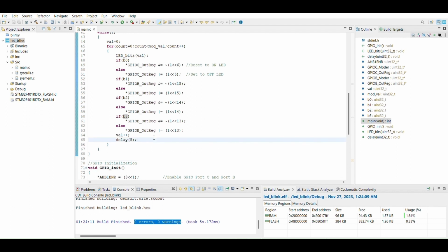in that software. In the Proteus, one thing we have to remember, we need a hex file for that. So I need to generate a hex file. See here, I have created a hex file here. It has built a hex file here, but by default it won't do that.